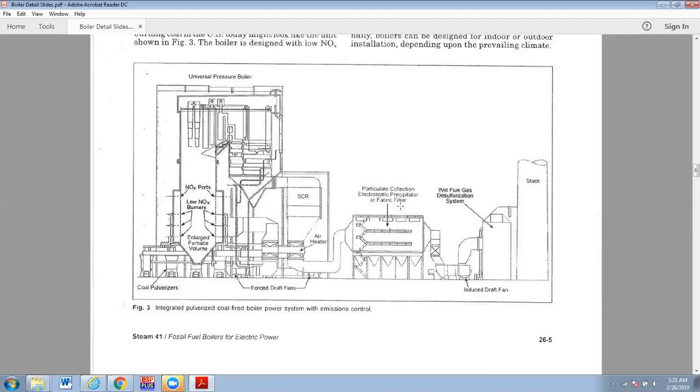So there's a whole system that has to keep that water chemistry correct, and then the gases pick up. They're essentially saturated when they come out of that bath, and then they are blown up the stack. So at Kingston, especially on a cold day, you see these white billowy clouds coming out of the top of the stack, and that's because they have scrubbers, wet scrubbers at Kingston, and so that's the water that those flue gases have picked up while they went through that bath in order to capture the sulfur.